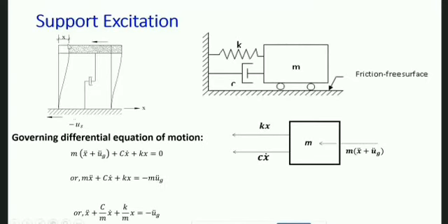If we multiply that displacement with the stiffness of the structure, K, we get the maximum force, or maximum shear, occurring in these columns. From that we can calculate the bending moment in the column and design the column for that bending moment. So that is the philosophy.